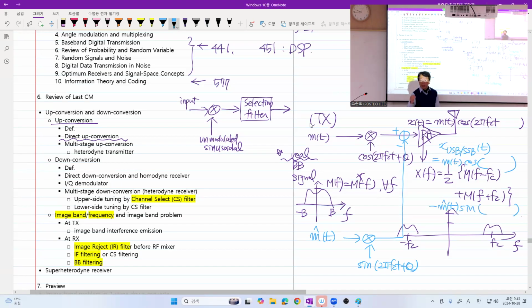And actually, in digital communications, we do not want to waste spectral efficiency. We want to increase the spectral efficiency. So most of the time, we have not only the in-phase branch, we also have a quadrature phase branch in the transmitter. Got it? So this is a more general direct up conversion transmitter structure. The problem is that if the carrier frequency is very high compared to the current technology, probably the cost of current technology, then